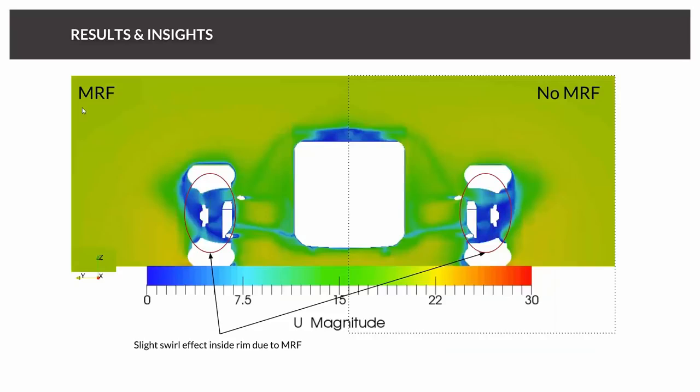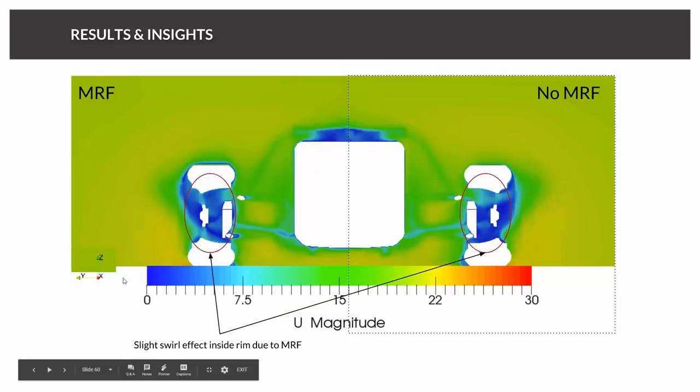The next thing I would like to talk with you about is MRF. And there was a question by Konstantinos. And here you can actually see why it's important, because if you only use wall velocity, you will only capture the effect of the rotating wheels, but not the effect that your part is really rotating.